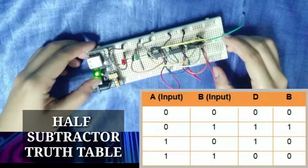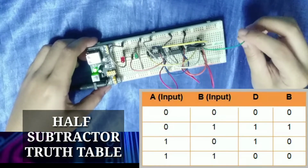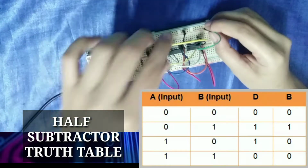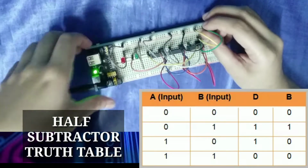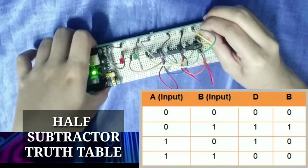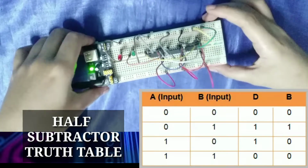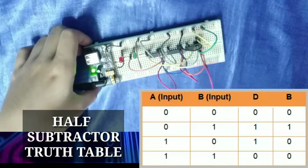Now for our truth table, let's turn on our voltage supply. If both of the inputs X and Y are connected to the ground, as you can see, our output will be 0 for the difference and for the borrow output, meaning both of the LEDs are turned off.